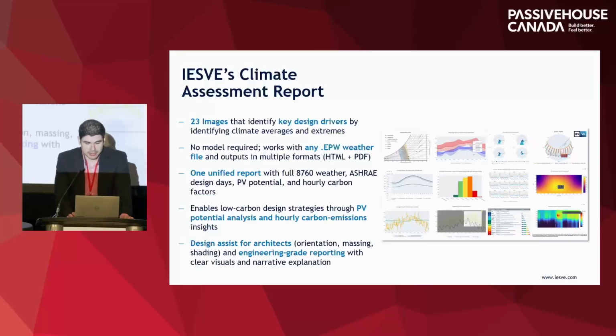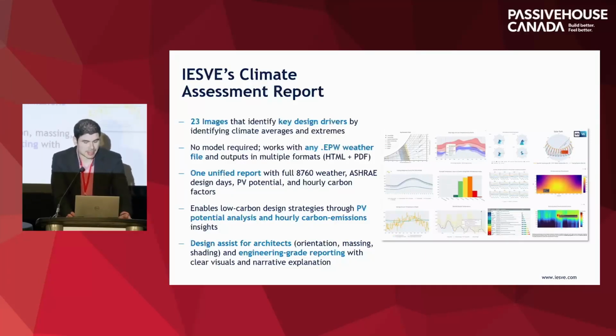Another feature that we added recently is our climate assessment report. This report contains visuals that are designed to quickly surface the key climate drivers so teams can identify what really matters for sizing and design conditions without digging through any raw data. Although you can ultimately build a full simulation model, all you need to generate this report is a standard EPW weather file that you can export to multiple formats like HTML or PDF.